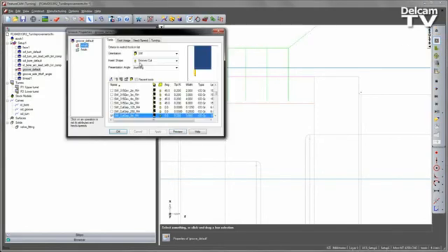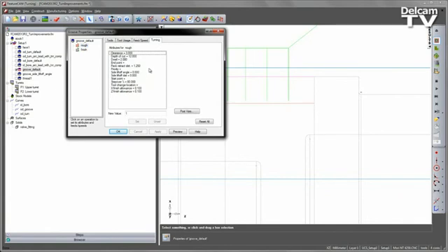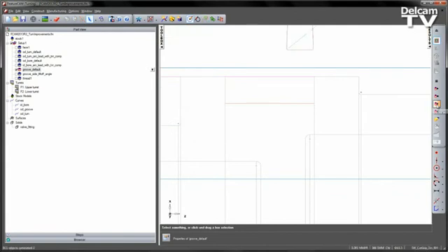I can check that by going into the roughing, into the turning tab, and you'll notice that we have a side lift-off angle and a side lift-off distance. In this example I'm going to set my angle to be 45 degrees. I'm going to set a lift-off distance to be 2 mm. I can now re-preview that toolpath.